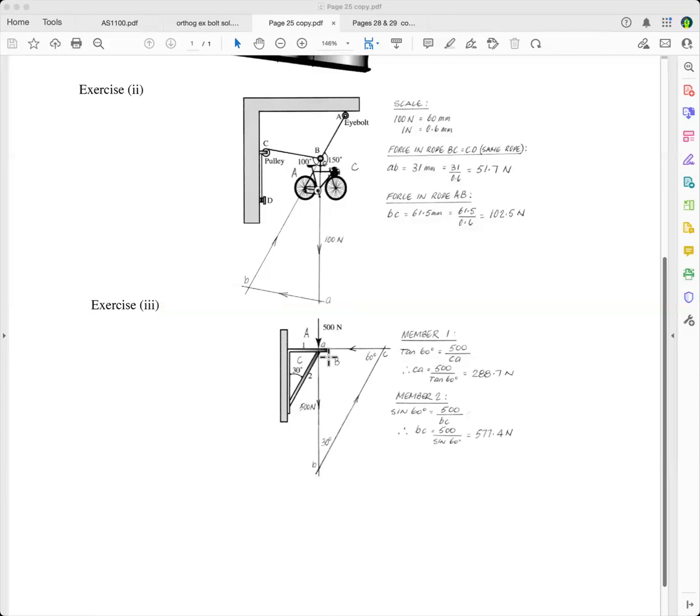And I like to name it. So this force here is AB, so that's little a, little b there. Then you come around, you've always got to read Bow's notation clockwise. If you go that way, you're saying 2 + 2 equals 5. Always go this way. And so we go around to this force here, which is BC. It's got to go through B. It's got to be parallel with that. We don't know whether it goes up or down, so you just draw that line through there.